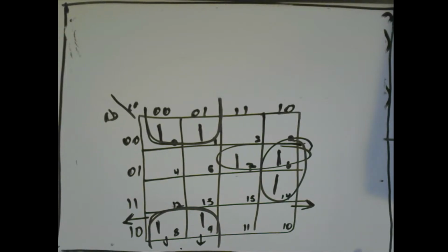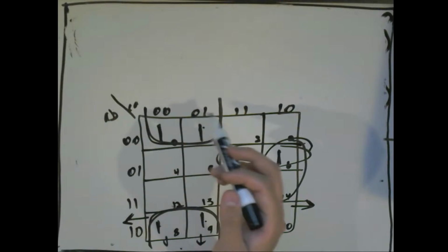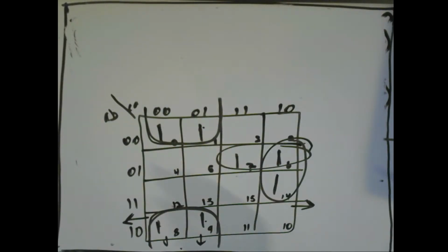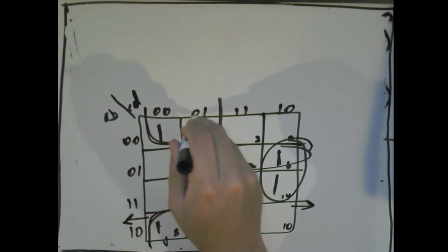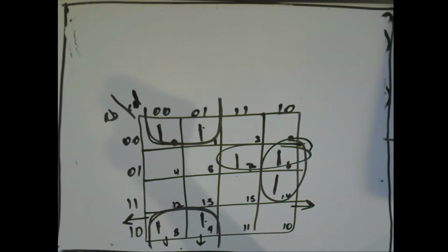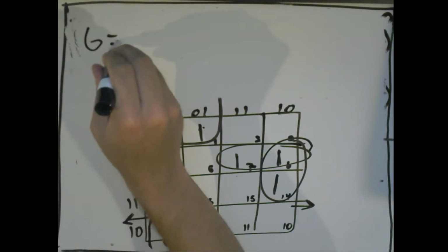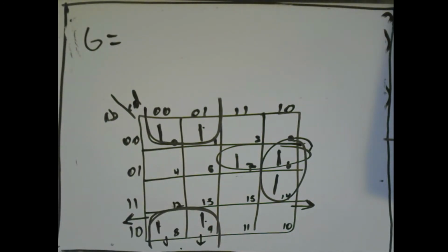So how do I write the equations? Well, I'm going to look at this grouping. So I have this, and this. This is all in the same prime implicant. And I want to see how these numbers change on top. I can see that for C and D, it goes from 0, 0 to 0, 1. And I want to write down how I'm going to form my equation. So this is going to be the new G simplified. How I'm going to write this down is I'm going to look at what variables change and what variables don't change.